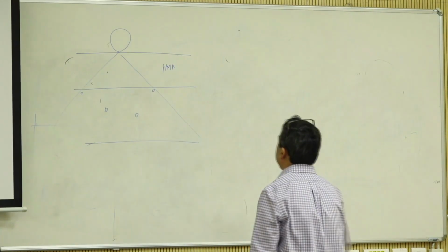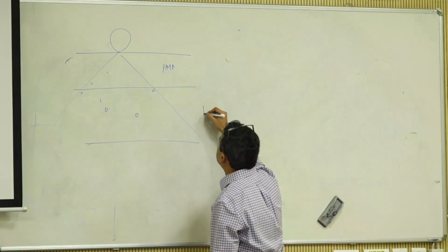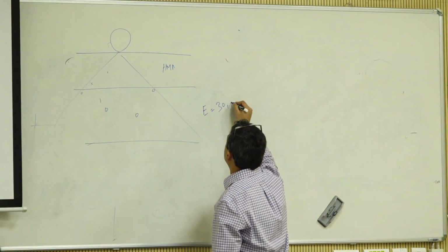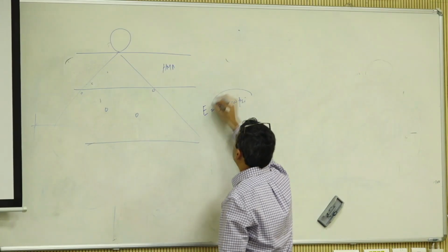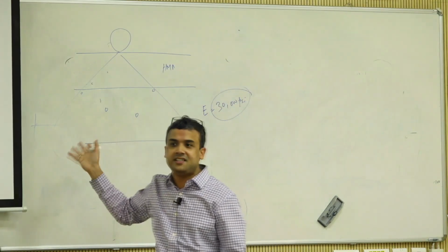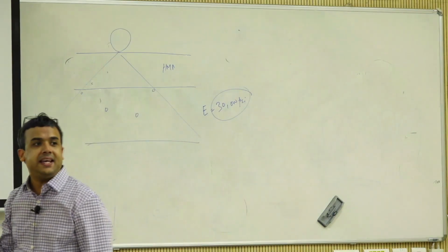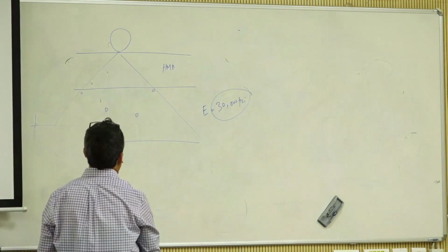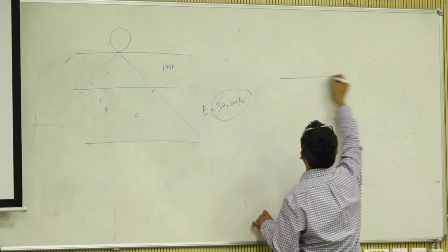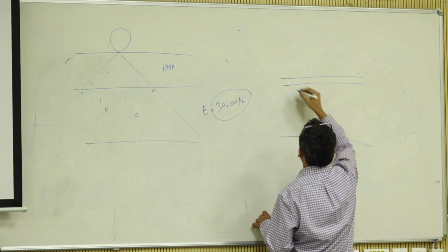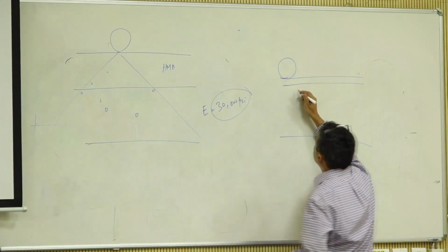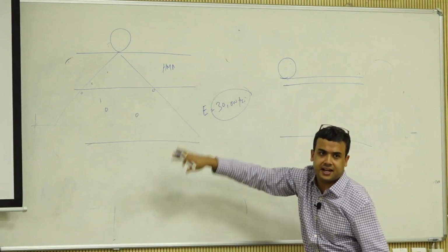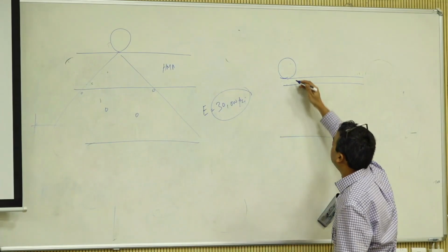On the other hand, if you are doing an AASHTO design or any other design, in fact even in the MEPDG for now, you are saying that E is equal to 30,000 psi or something like that. What does this mean? Where is it? In an aggregate layer, if you just model a very thin asphalt surface and then just aggregate and you do an axisymmetric model, this is axisymmetric, so there is a pavement on this side as well. I'm just drawing the boundary at one side.